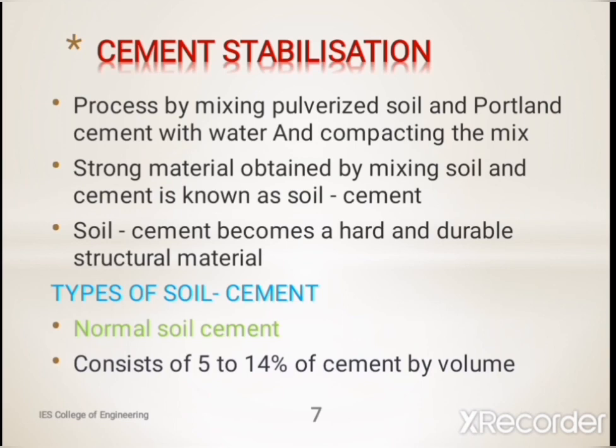Next, we discuss cement stabilization. It is the process of mixing pulverized soil and Portland cement with water and compacting the mix. Pulverization means the crushing of soil to fine powder by mechanical means. So, the soil is crushed into fine particles of size less than 5 mm.